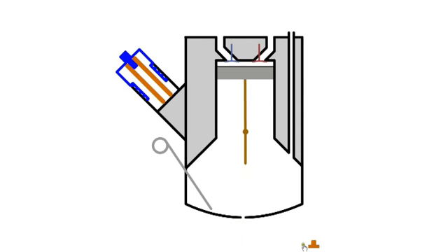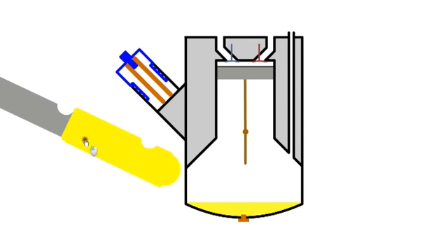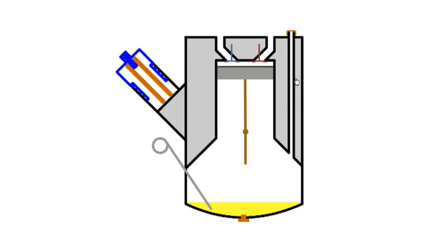Dispose of the old oil in an environmentally friendly manner and tighten the drain plug. The sump is now filled slowly with new oil to the desired level. When the oil is allowed to settle, the level can be checked with a dipstick. The level should be at or just under the high level mark. Fit the oil cap and clean any oil spills.